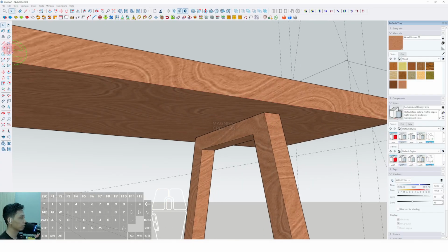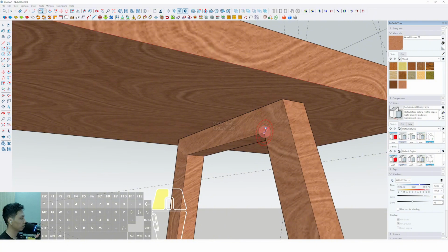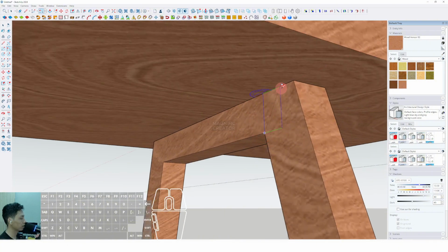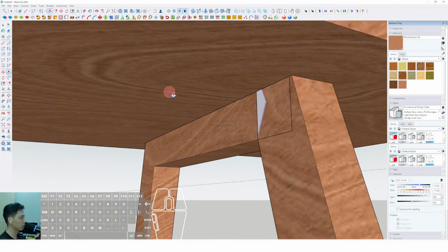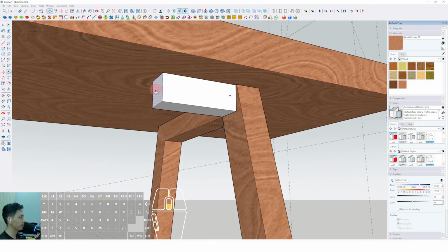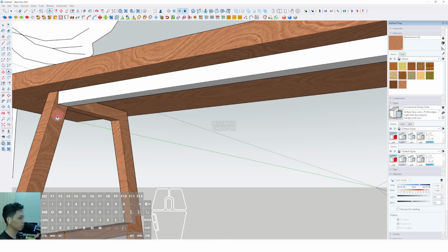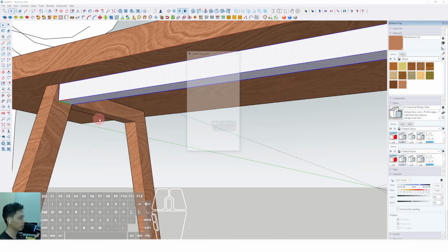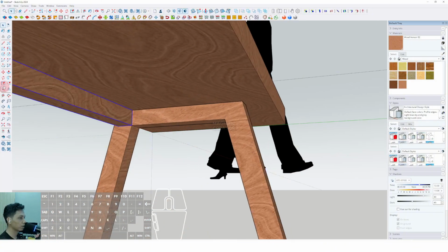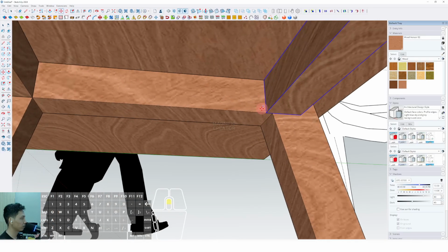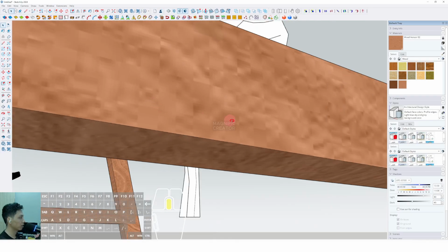Then we can make the strengthened frame like this in here using the rotate rectangle. Click this corner and click this corner, and we can click this corner again around 30 millimeter and enter. And we can click the surface, click push pull, click the surface and click to the surface and triple click, right click and make component, create and assign the materials like this, and we can select move, tap control, and okay, we can fix this placement like this.